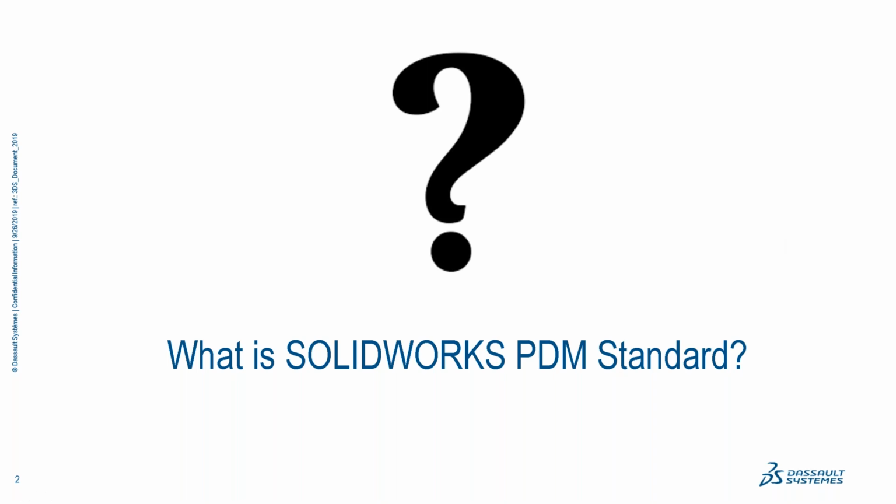A little bit about the architecture of SOLIDWORKS PDM Standard. The physical files are stored in what we call an archive server, and the metadata, like information about your files, revision, description, material, all that information, is stored in a database. And the backbone in the background is SQL Express.